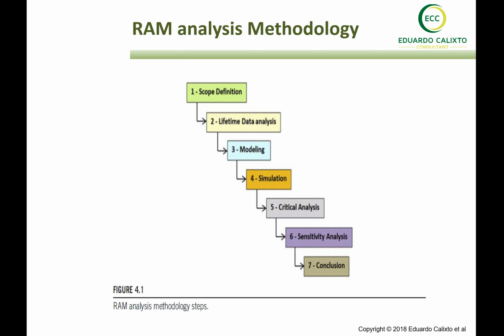It's important to say that the RAM analysis involves a lot of statistics, but also the experience of the engineers and technicians about the equipment supports the result. So in many cases, we can justify our choice during the lifetime data analysis based on the experience that we have, that we know the reality and we know which function will, for example, best represent the data that we are collecting.